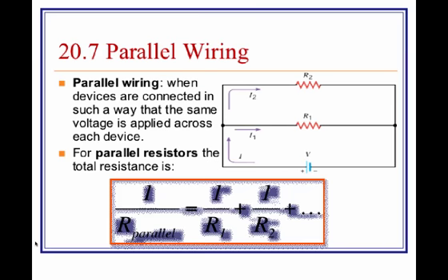In a parallel circuit, there are many distinct advantages that help us out in our daily lives. The main one is that there are multiple branches, and across each one of those branches is applied the same voltage. So when you have multiple branches connected to a power supply, for example our wall power supply of 120 volts, there will be 120 volts of potential across each one of those branches.